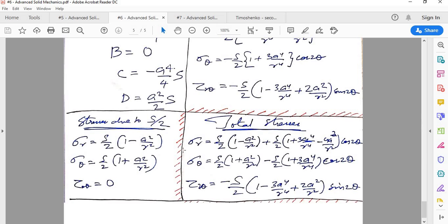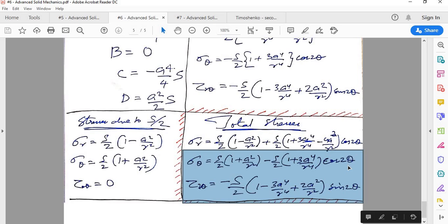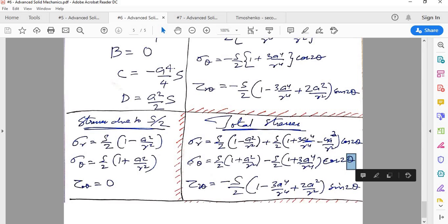So if I am giving you the ratio and theta, using theta you can first simplify the expression, and then when you take the ratio of any two stresses, you can see that S, the external stress, is cancelling, so you don't need that. Then it will be like an equation in the fourth power of a by r, right?